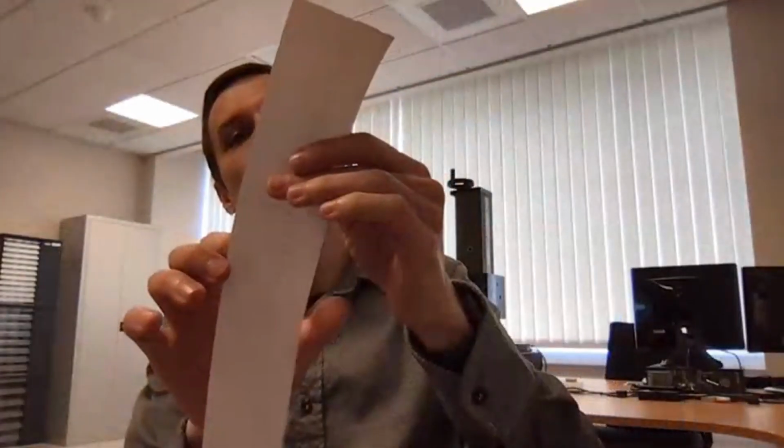Because let's say if this is our, okay, this is maybe not the best example, but it is also important to see these profilograms, because you can then see whether your surface consists of a relatively flat area which contains some sharp asperities on it, or it is more or less a smooth surface with some sort of dimples or valleys inside the surface, because it would change dramatically the way this specific surface can perform its duties.